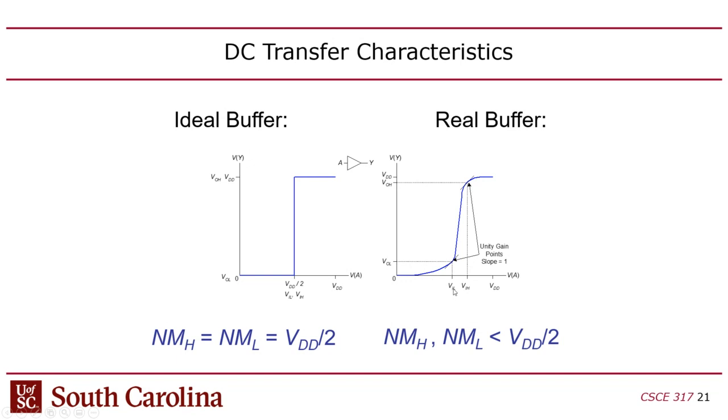So you're going to have VIL, which represents the voltage of the input low, and then you're going to have voltage output low. What VIL represents is the highest input voltage that would be considered a 0 in the eyes of the input of the gate, right? The gate will assume that anything below VIL is a 0 input, and likewise anything above VIH will be considered a 1. So this is basically just taking a voltage and converting it to binary. But this is for the input.